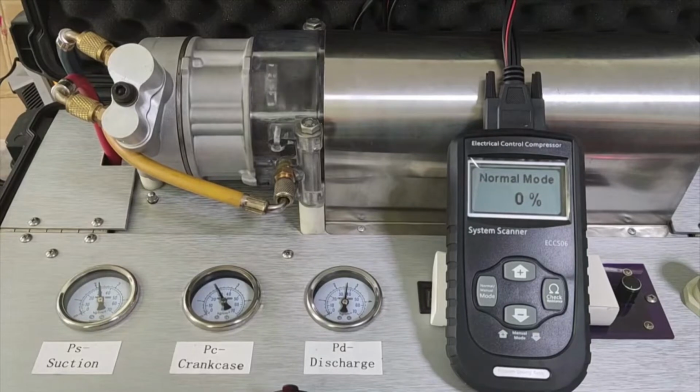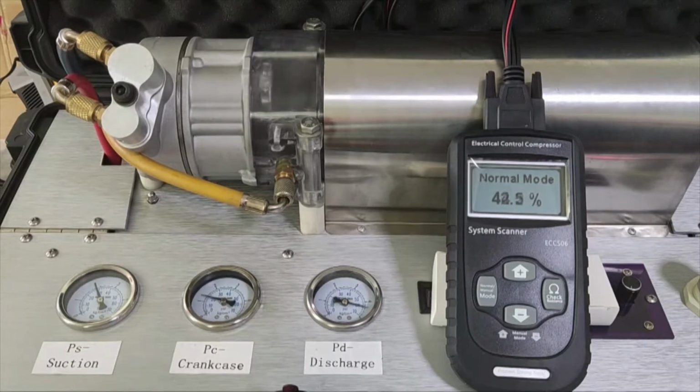The pumping displacement of a variable displacement compressor can be varied smoothly and seamlessly to precisely match the changing heat load on the system. This avoids the necessity to constantly cycle the compressor on and off. A variable displacement compressor uses only the minimum energy necessary to meet the demand on the system. The result is improved fuel economy, reduced emissions, and a smoother idle.